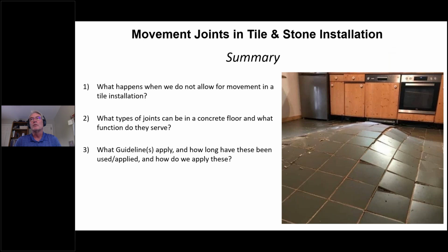But as I touched on, years ago, let's say we had a saw cut in the slab, and somebody came to us and said, we don't really want to cut our tile where that saw cut is. Do we have to? You might say, no, we've got a crack isolation membrane that you can go over that saw cut with. But the problem is you can't really make that a standard recommendation today at all, because tile types are so different, concrete slabs are so different.